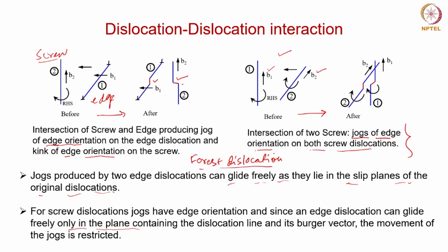This essentially means that the dislocation density is increased due to the cold working which is given to the material, and as a result of that, a lot of dislocations are present in the path of other moving dislocations, right? So this kind of dislocations is also known as forest dislocation.